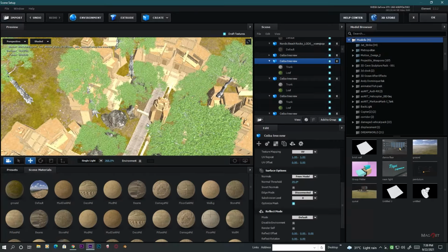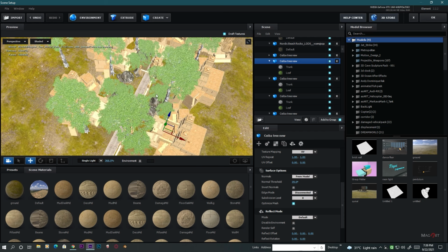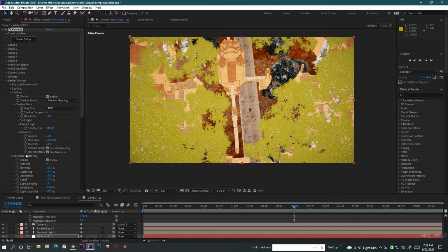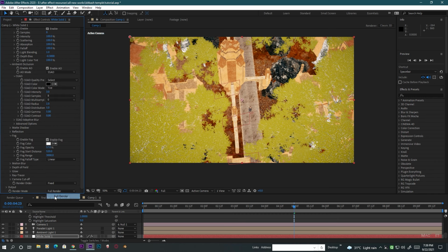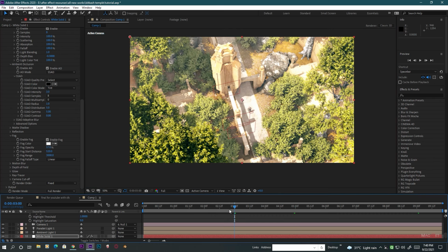Okay, so you can also do this at the beginning of your scene, so you will not have to do the same for every model which you replicate at different times. So now just hit OK, and again we go to our full render here, and we will see nothing will change, but it works internally, and you will not notice anything change here, and there is no change in quality as well, but your render time will be very much less if you turn on the optimize mesh option.